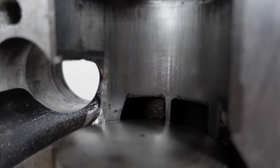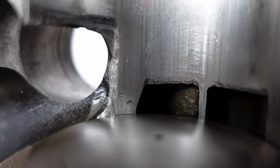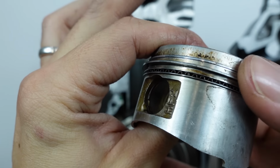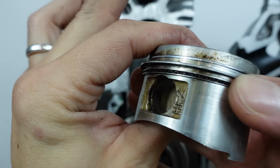This is done to prevent the piston ring ends or gaps from snagging onto the exhaust or the transfer ports, which would lead to engine failure. Instead, the rings are fixed to ensure that the gaps always travel over the area between the transfer ports to eliminate the possibility of getting snagged by the ports. The free-floating ring system of the 4-stroke is actually superior because allowing the rings to rotate can help ensure more even wear of the rings and a longer-lasting engine.